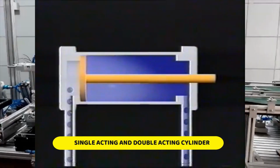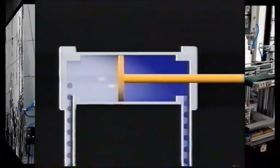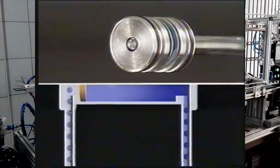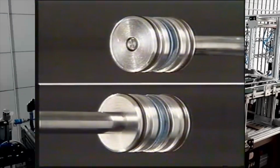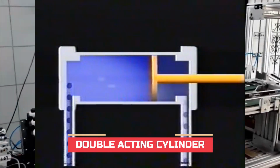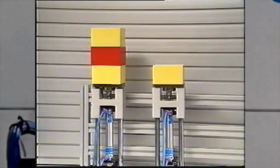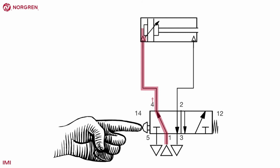There are two common types of cylinder, single-acting cylinder and double-acting cylinder. A single-acting cylinder is one where output force is developed in one direction only. The piston is returned by a fitted spring. A double-acting cylinder is one where the thrust or output force is developed in both the extending and retracting directions. A double-acting cylinder has a port at each end and moves the piston forward and backward by alternating the port that receives high-pressure air. It is necessary when a load must move in both directions, such as opening and closing a gate.